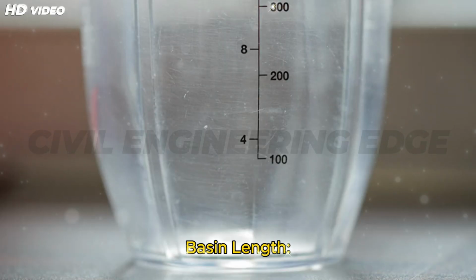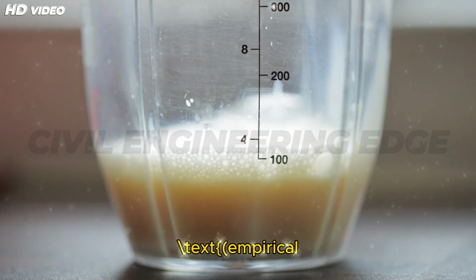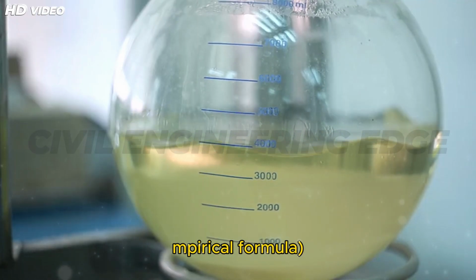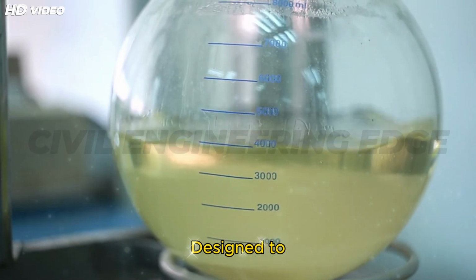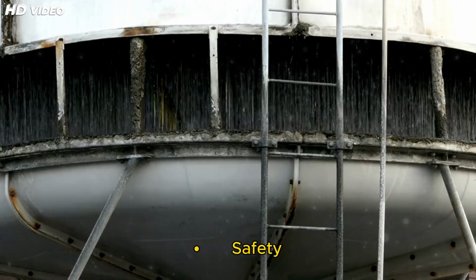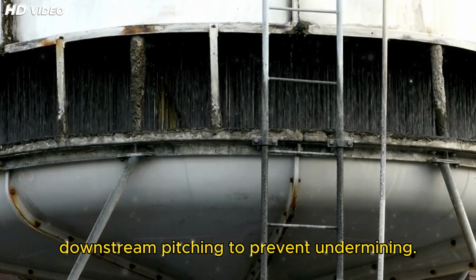Stilling basin length: L equals 6 times D2, empirical formula. Tail channel transition, designed to gradually return flow to normal depth. Safety features: curtain walls, drainage filters, and downstream pitching to prevent undermining.